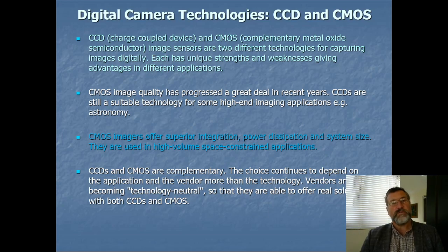Another thing that's important that is often not mentioned is the size of the actual sensor. If you look at something like a digital SLR camera, you'll have quite a large sensor in it. That's because they want a nice, good quality image. Well, we want that in machine vision too. So a larger sensor with bigger pixels means you get more light going in, you get a better signal-to-noise ratio, and you get a better quality image. Generally speaking, you won't need such a small focal length on the lens, so you'll get less distortion as well. But of course, it costs more.